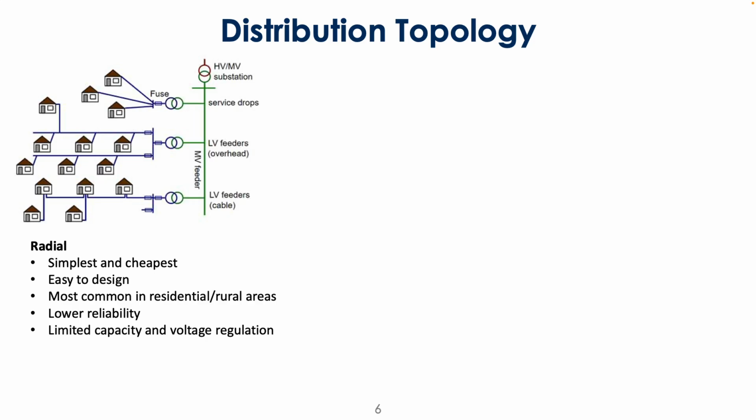So essentially, here is the notation for this network. The brownish reddish is your high voltage transmission, and then you have a substation. The two rings essentially denote transformation down to a lower voltage. Green is our primary distribution, and blue is secondary distribution. So you have another set of transformers here to drop the voltage from primary to secondary.